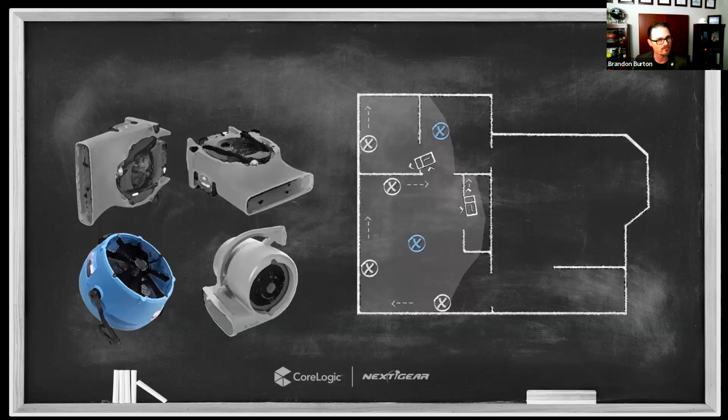So there's best practice on installation, the best way to put in our general air movement. I want you to also note, however, that as soon as these air movers are deployed, you should verify that these air movers are properly moving air along all of the wet surfaces. And there are two ways to test this. One way is the hygrometer test that we've already discussed at length in previous episodes. And that is just making sure that the air at chest height is the same as the air down at foot height. Right? Same temperature, same humidity.